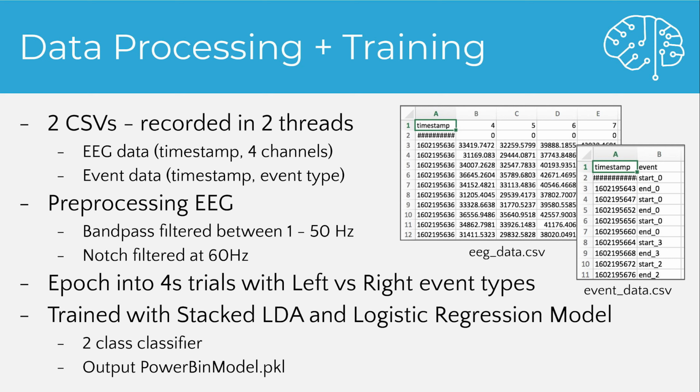Of course, as the finished app records the EEG behind the scenes, it saves the dataset in the same format as well. The dataset consists of two spreadsheets, the EEG data and the event data. The EEG data contains the electrode readings from the 4 electrodes every 4 milliseconds, and the event data logs the trial types, a timestamp at the beginning of each trial.